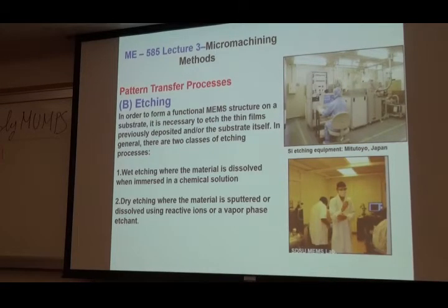Again, remember that lithography process that we did. We kept the photoresist while it was protecting some areas from being attacked. And here's where it becomes interesting. Polymers look weak, but they're good. There are some acids which will eat metal for breakfast, but they don't attack polymers fast. That's what happens here. All the etchants that I'm going to use, whether I want to etch silicon or metal, will etch the metal. You can see it, in fact, in front of your eyes. But the polymer stays. Of course, if you keep it long enough, it's going to be etched. Okay?